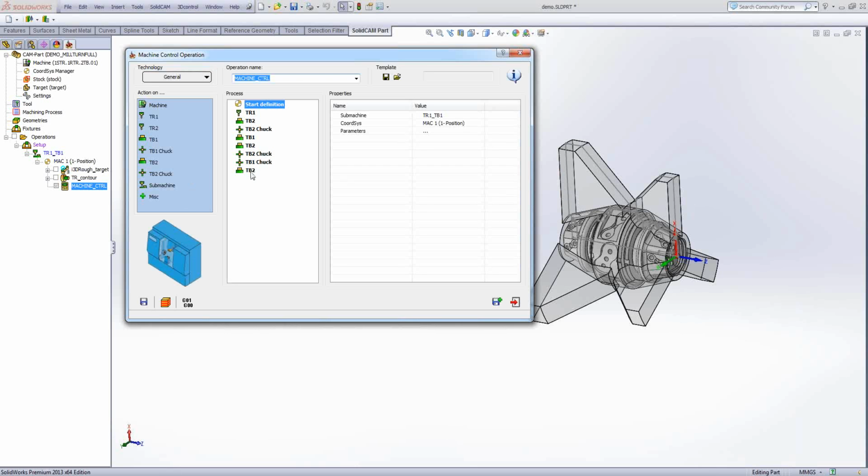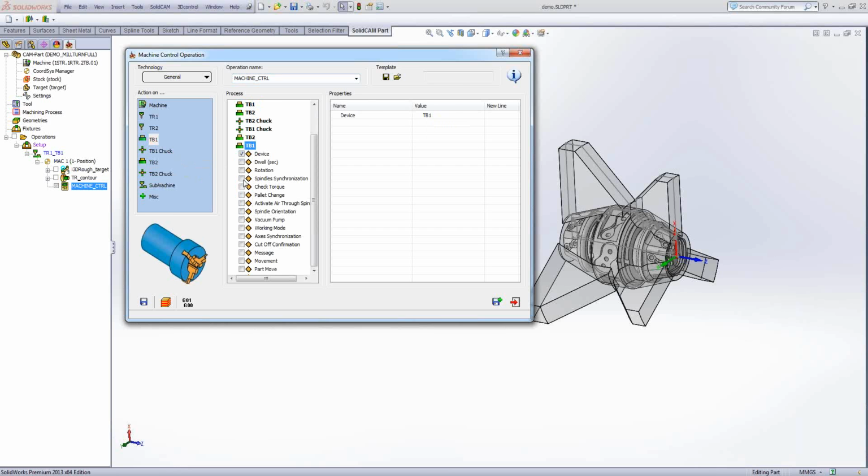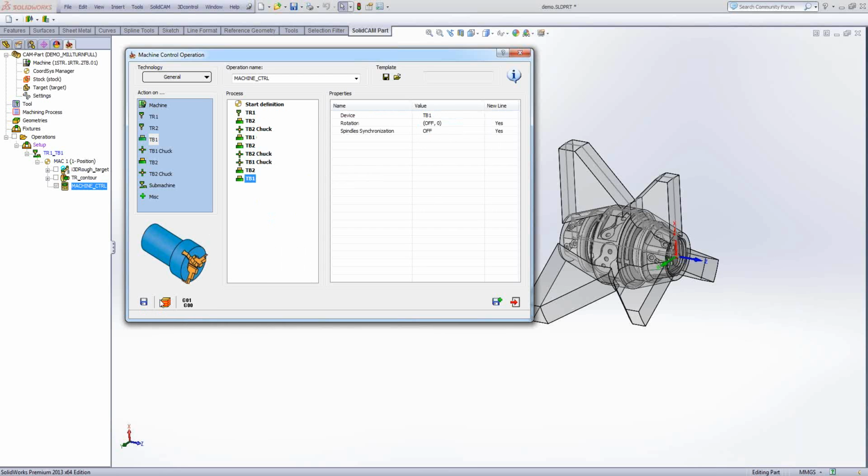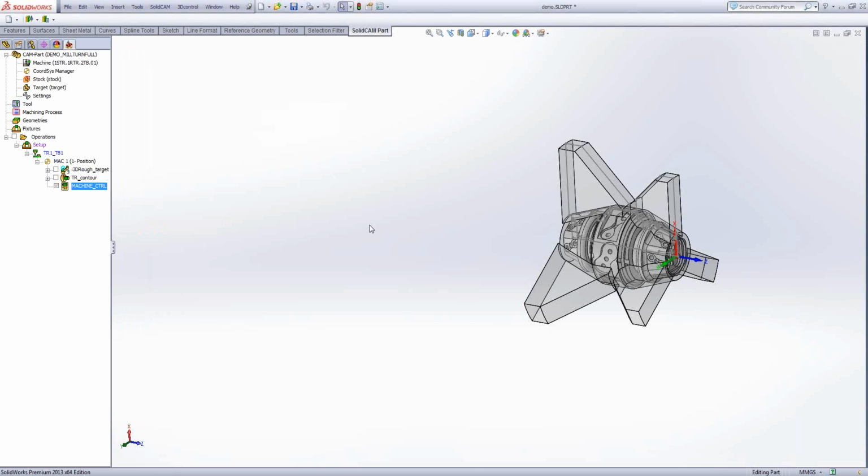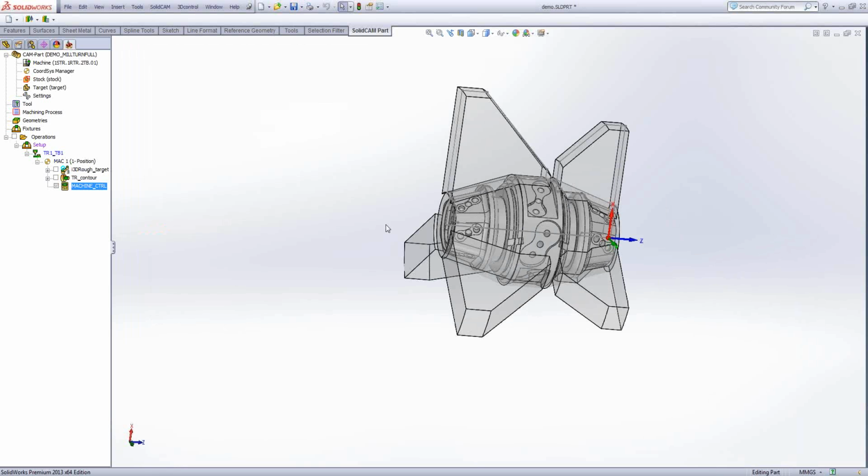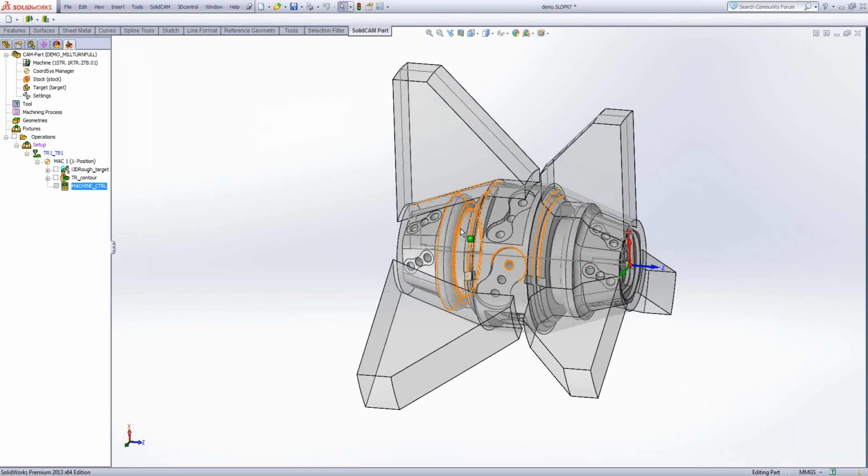After the back spindle reach the reference point, now table 1, stop the rotation off, and also the synchronization off, save. This is for G-code more than for the simulation. Synchronization and rotation.